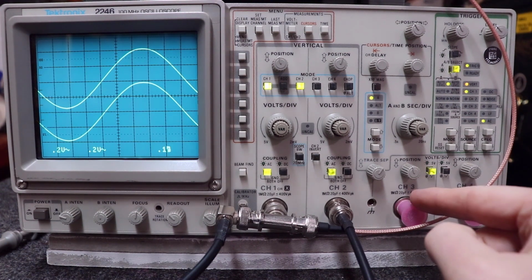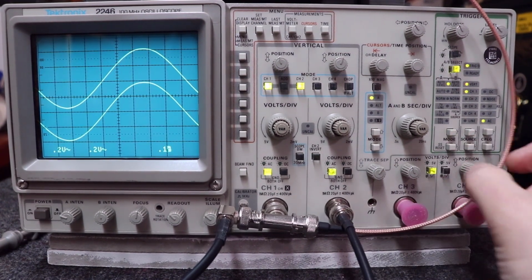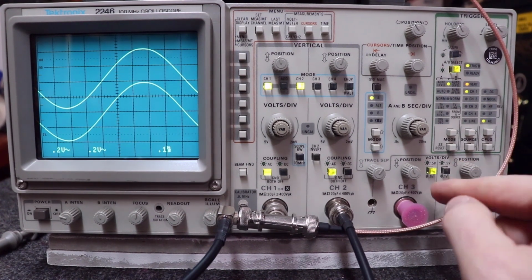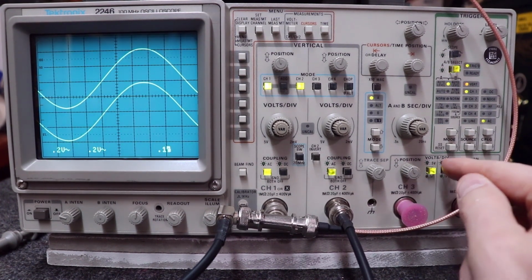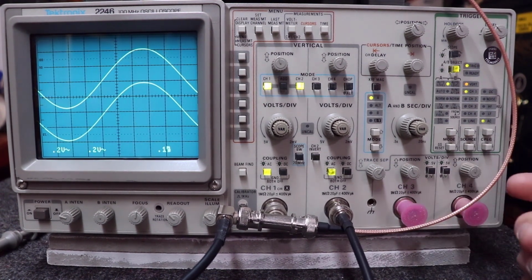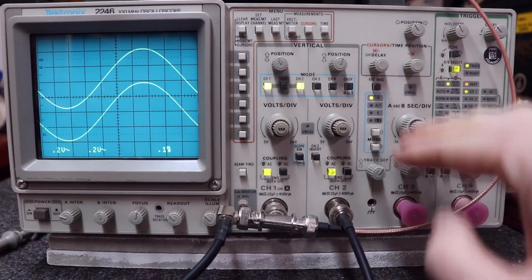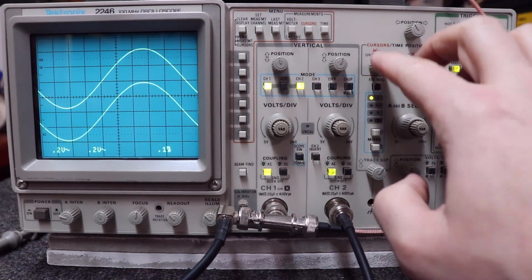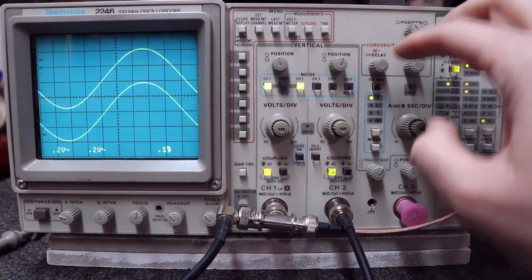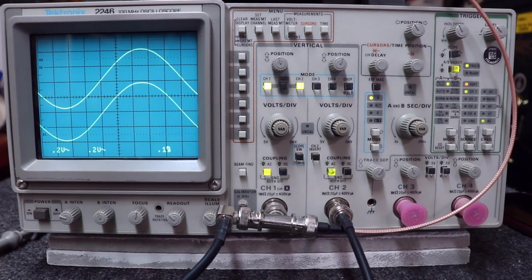So in reality, all you have left on the horizontal side here is the position of channel 3, the position of channel 4, and the volts per division markers that they have for each of those channels. That's really it as far as vertical and horizontal goes. This right here, we'll talk more about in a little bit, and then position, as we talked about earlier, is left and right on your signal.